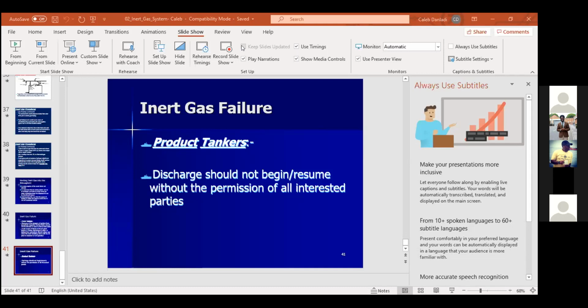No, it's not a requirement. It's only a requirement when you are carrying low flashpoint cargo, defined as cargo having a flash point of 60 degrees centigrade on a closed cup test. But if you are carrying that particular cargo, because you can supply bunkers that have different grades of oil. I've inspected a lot of bunker barges and none of them is fitted with an IG system. They don't even have the IG generator.